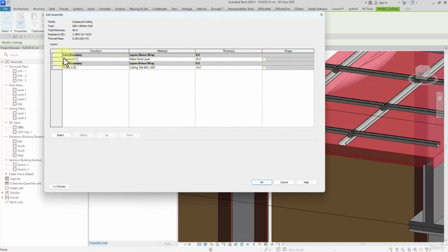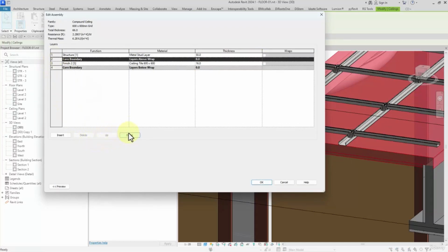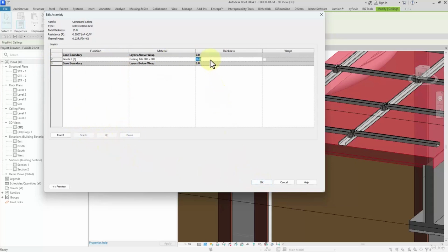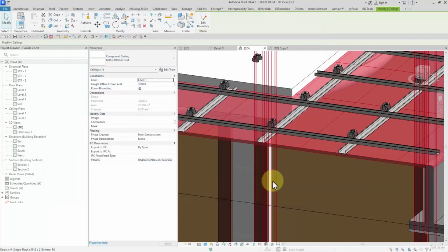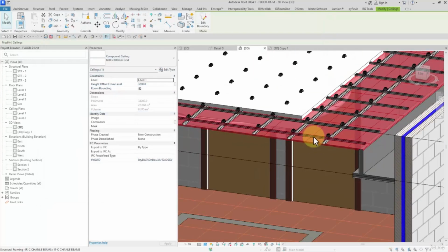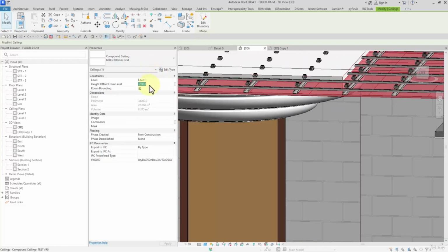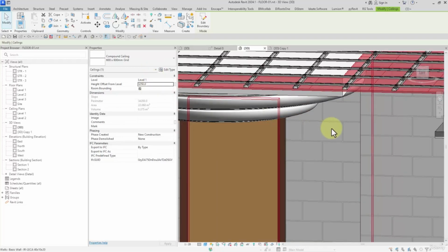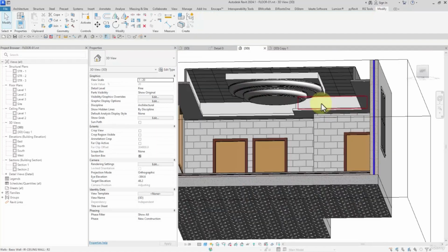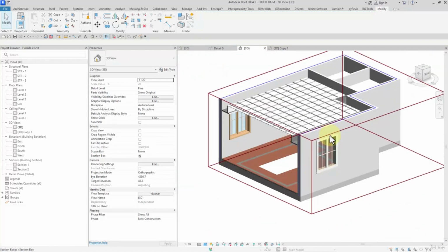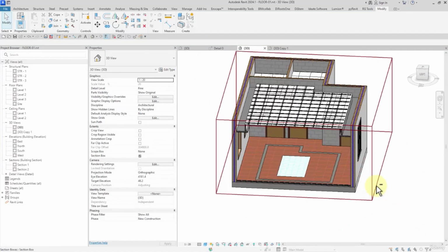Then here we can brush aside the thickness of the panel, and I can delete the thickness here. And we only consider the thickness for the ceiling when we don't want to display the substrate. So we delete the thickness, watch this. And since the connections were hosted by the ceiling, we have to adjust their heights again, 3250. And here they are.